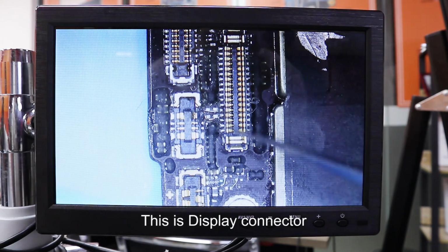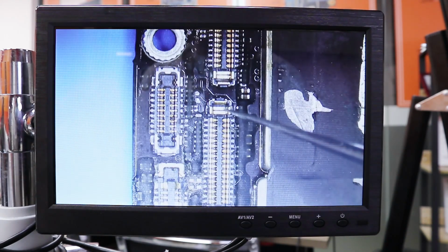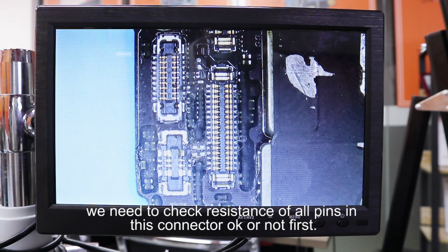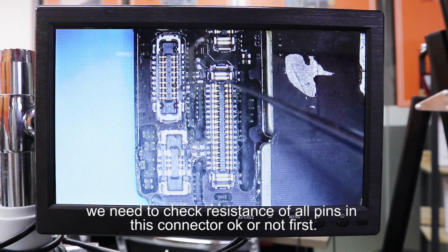This is the display connector. Before we repair the display circuit, we need to check the resistance of all pins in this connector, okay or not, first.